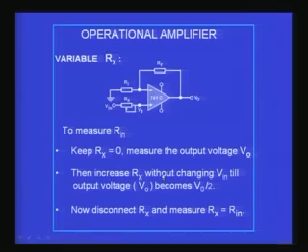If I have two 200k resistors connected to 5 volts, and I measure the voltage across one of the resistors, you would find the voltage will be 2.5. The resistor is basically a linear device, and therefore the total voltage is split into half, and each of the resistors drops equal values of voltage, which is V by 2. Therefore, this will happen when the two resistors are equal. One resistor is the external resistor that I have deliberately connected as a potentiometer, and the other resistor is the internal input resistance at the input terminal.